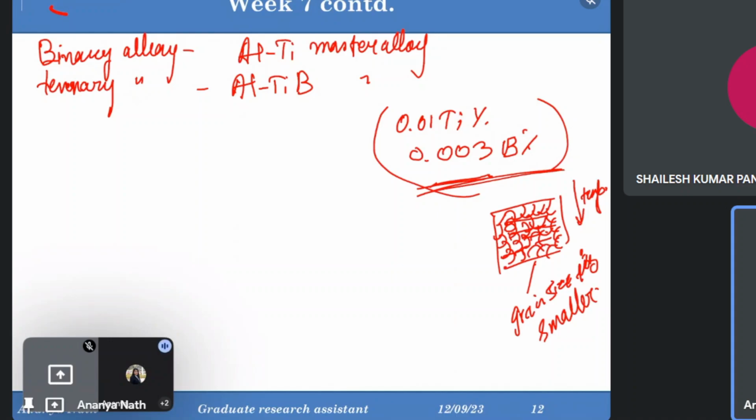High temperature slow cooling will give rise to acicular type aluminides. And low temperature slow cooling will give rise to equiaxed, attributed to the change in interfacial energy with temperature. So Al3Ti, which is also added, will be formed in the form of intermetallics, which will have some number of facets. So it's like we have said, in the melted or liquid metal we have added the inoculants or the inclusions, but how will the inclusions help?